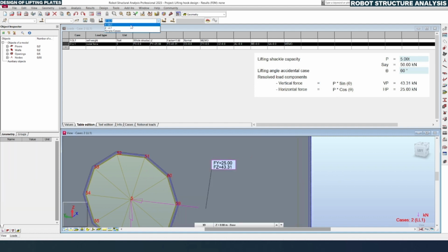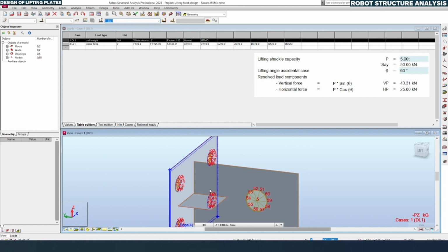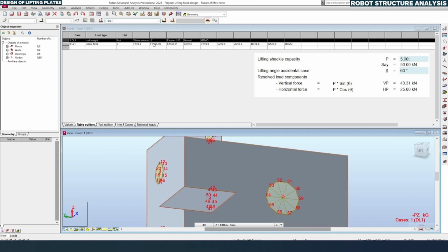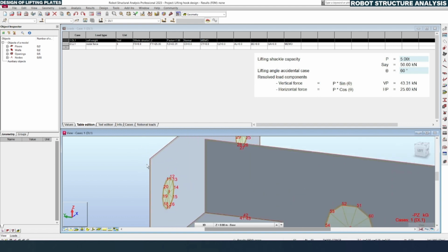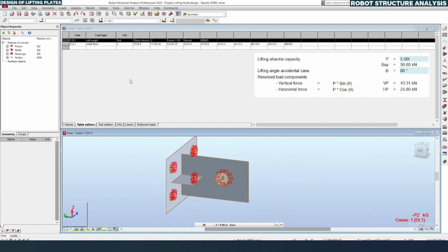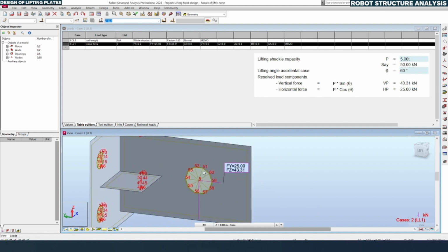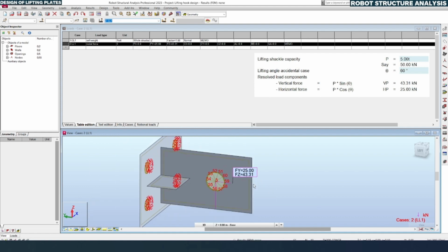For dead load, if you select, this is selecting the entire plate in blue color, and a red color line is surrounding all over the plate. So it means the self weight is applied for the entire plate. Now the live load also you can see here after selecting this. So we had applied the necessary loads. Then the next step is to analyze.